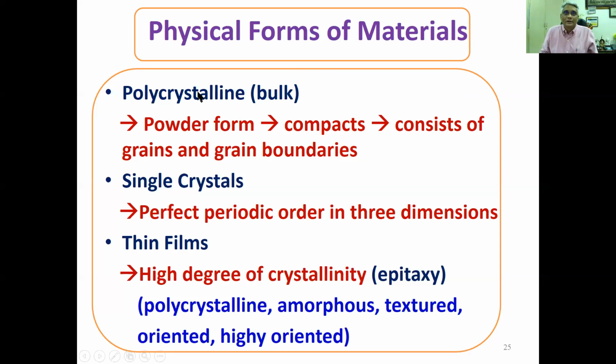These are all interesting things that you'll see how to realize. If you start with polycrystalline bulk material, of course, a polycrystalline bulk material is required if you want to grow thin films using a certain method. Remember, I also told you, if you're dealing with thermal evaporation, first I said physical vapor deposition requires solid or molten sources. That means I take a piece of metal, a bulk part of a metal, either in the form of a powder or an ingot or a small piece, and just melt it.